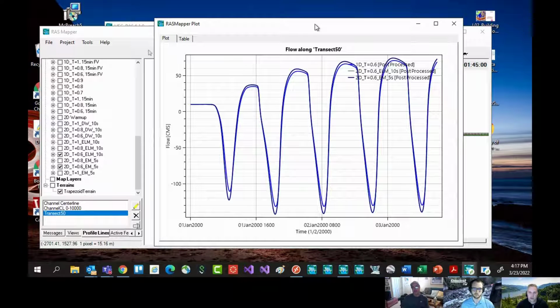So I think the new solver is really important where you have sharp contractions and expansions in your river system, because the spatial variability of the velocity is dramatic, and that's the tracking method. It's hard to track where the velocities are coming from in sharp contractions and expansions, and where they're going. And that's where the original method, the tracking, you start to get a little bit of numerical attenuation of the inertial terms because of that.